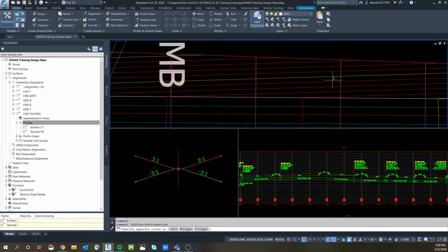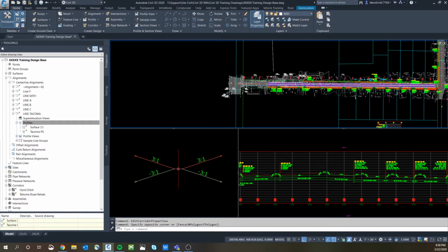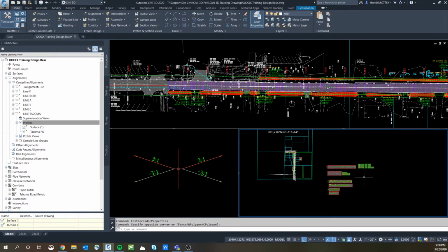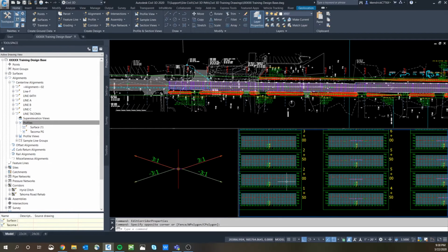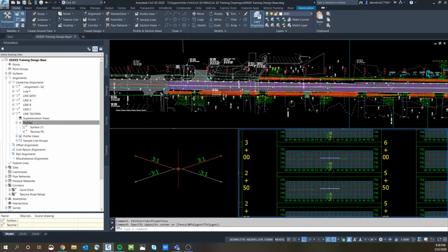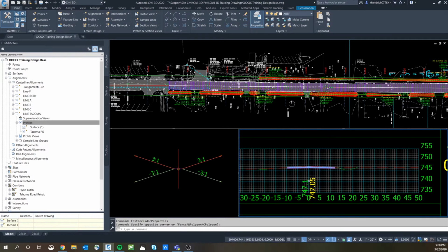We have a ditch here. It looks like a ditch. If you look at it in cross-section view, you can see what it's doing. This is down the center line of the Tacoma alignment that I used for the road. And on either side of the road, you can see what the ditch is doing, tying into existing.